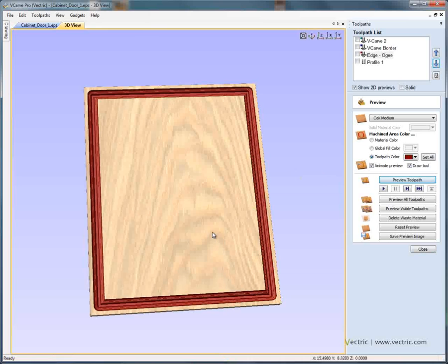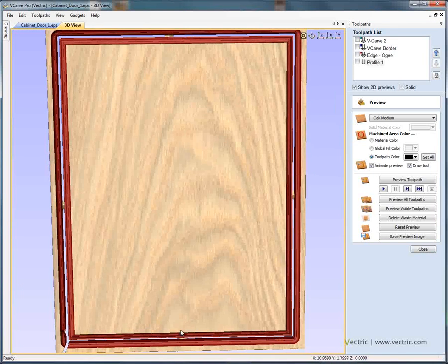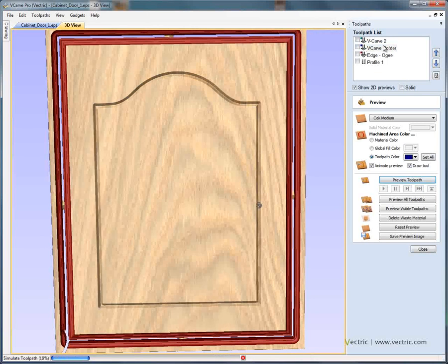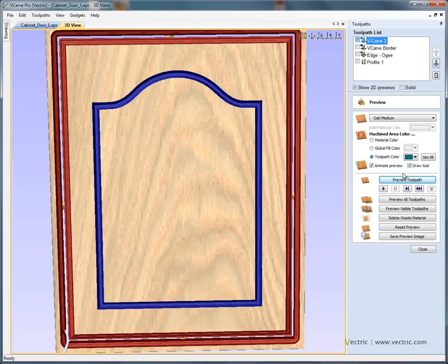So this is going to form the edge, and we profile machine to cut the piece out. We've got little tabs holding the part in place, so tabs on the left, the right, and also on the top and the bottom. And we've got the decorative V-carving. So preview and preview again.